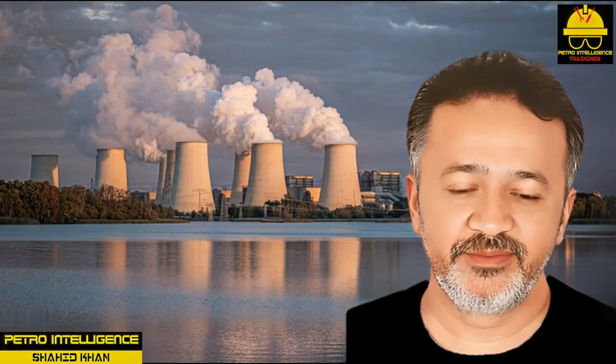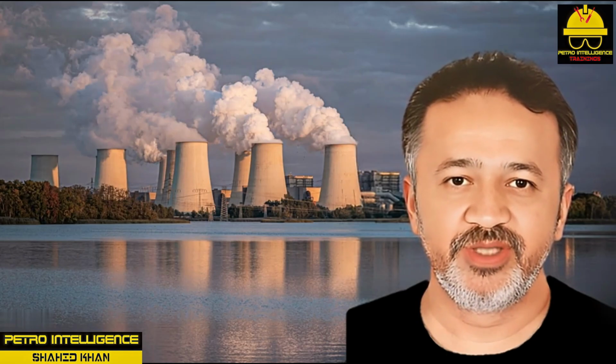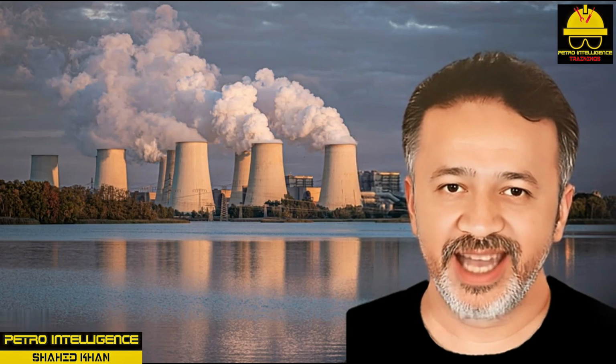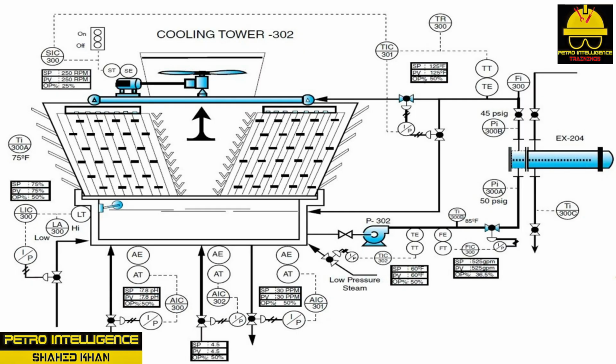Cooling tower efficiency, wet bulb temperature and humidity cooling. Since wet cooling towers respond to evaporation, relative humidity has an effect on the efficiency of the cooling tower system. Wet bulb temperature is taken using a specially designed thermometer and wick arrangement. In multi-cell operations, additional fans are typically applied. However, since CTW 302 has a single fan, the RPMs can be increased to improve airflow through the cooling tower. Higher temperatures will also affect the ability of the cooling tower to expel heat.